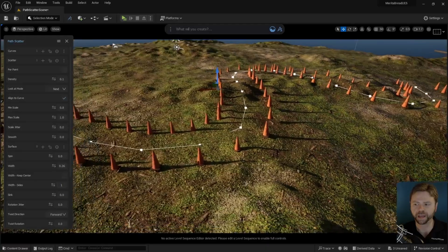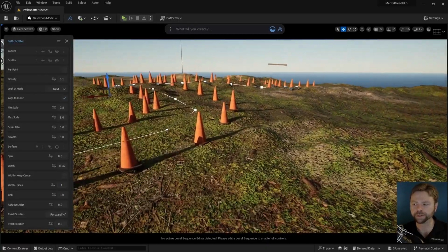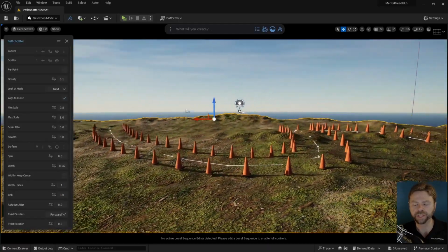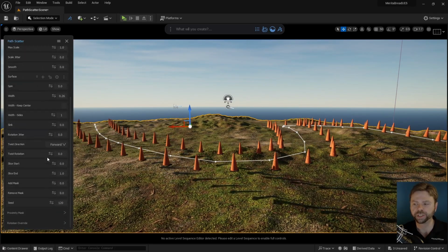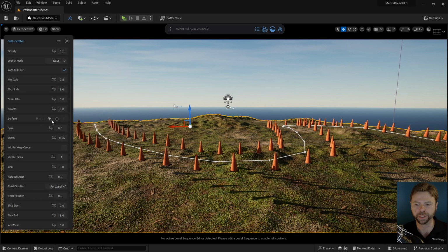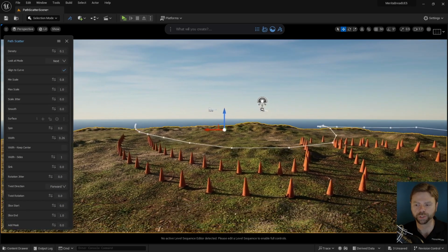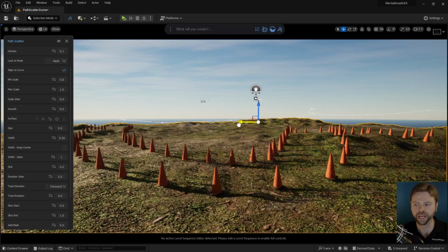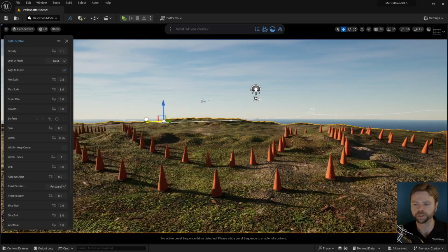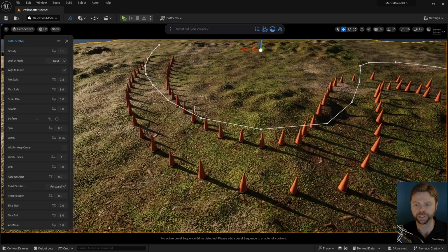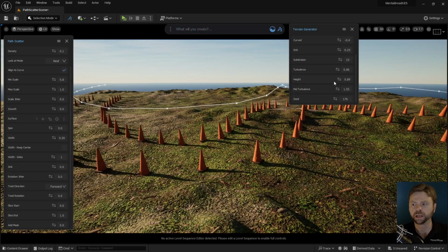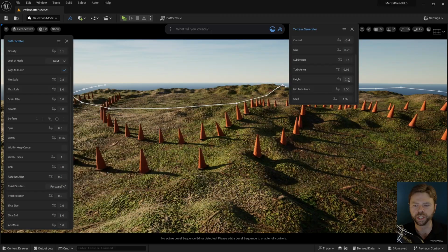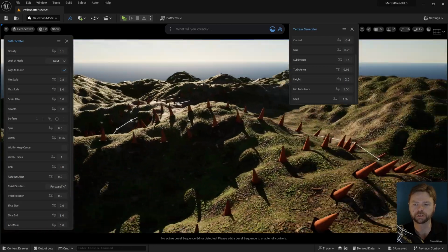You can use Path Scatter on underlying surfaces too, like the terrain here. Once added, the meshes and Path Scatter will only show up on the surface of the selected object. It actually doesn't matter if the path is above or below the object being scattered on, as the meshes will project to its surface and update in real time. This works whether you adjust the location of the curve, individual vertices in the curve, or the mesh being projected on. It even works if the mesh updates in real time, too. I can change its values and the scatter will adjust to follow the new geometry.